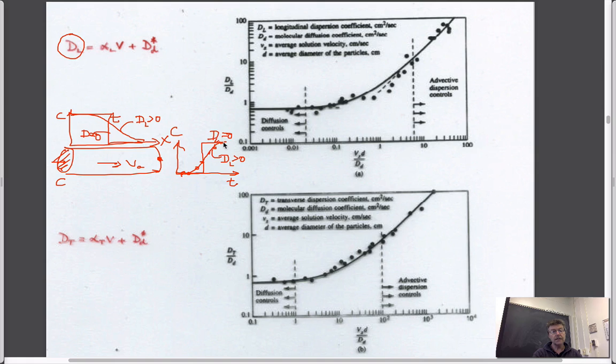If we have this residence time distribution, we should be able to calculate, although we haven't said how, what this dispersion magnitude would be. Right? So that's the experiment. What we could do is flow this at very small advective velocities, and flow it at very high advective velocities, and measure to see if this dispersion changes. And what we could do is plot it by dividing this through by d star.